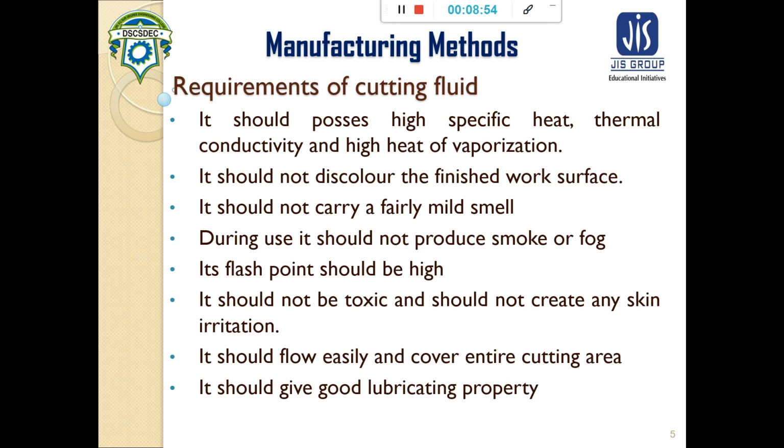So thermal conductivity should be higher, and a high heat of vaporization should also be there, because if the liquid is vaporized during application, meaning we add water to the chip tool interface and all of the water is vaporized, then there is no lubricant or cutting fluid at that chip tool interface. So that would lead us to a problem.